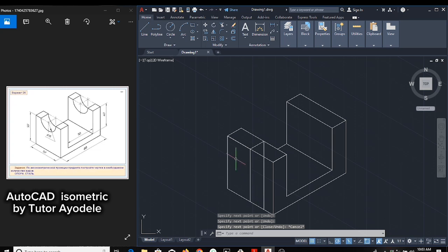What I need to do is get where this 15 will be. From here to here should be 15 as the radius that they give us here. So let's come 15. Let's pick the line command. Then we come to this point. We click on the point. We come here now, 15 millimeters. So that's the 15.